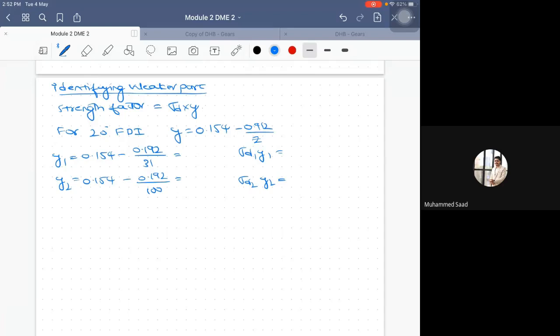So I will take it from the textbook itself here. So it is 0.1246 and 0.1449. Okay. Sigma D1 is 206.81 cross 0.1246. So the value is 25.7 megapascal. Similarly, 137.34 cross 0.1449. So here the value is 19.90 megapascal.